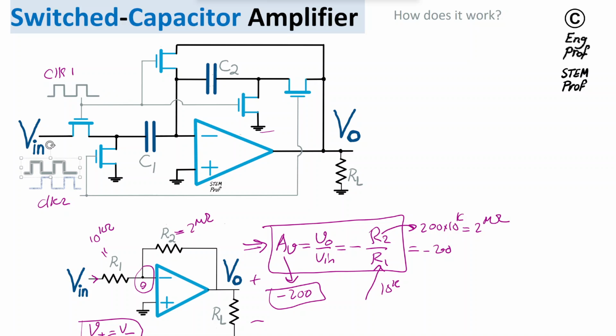Okay, so what happens is, when you compare these two clocks as an illustration, this is clock 1 and this is clock 2. They have exactly this sort of relationship. They have the same frequency and period. But when clock 1 is high, during this time, clock 2 is definitely off. When clock 2 is high, then clock 1 is off. So they do not overlap.